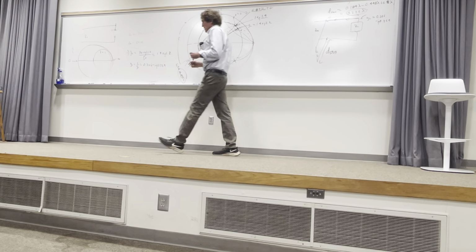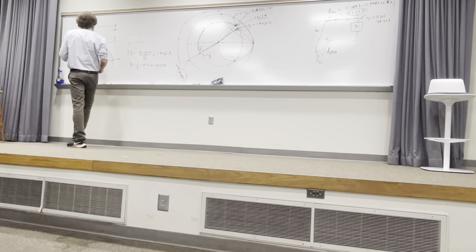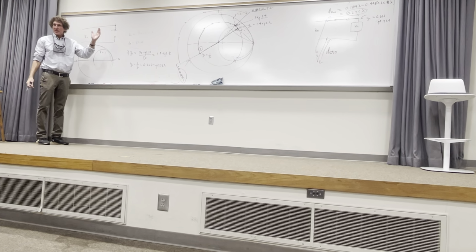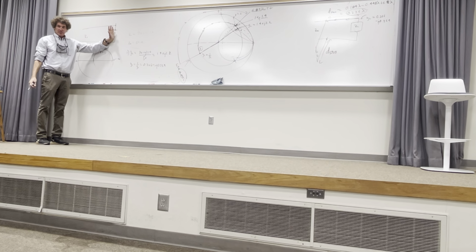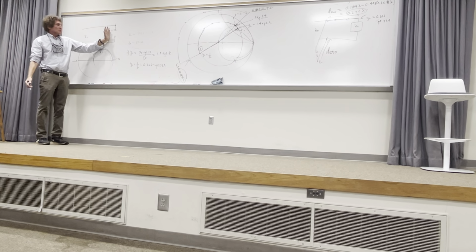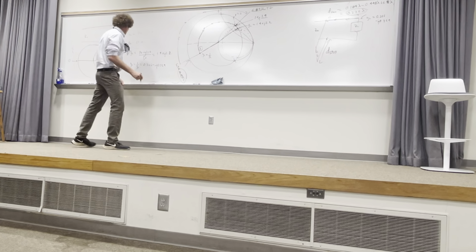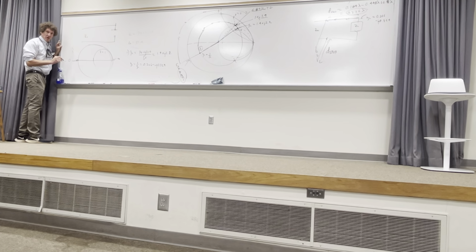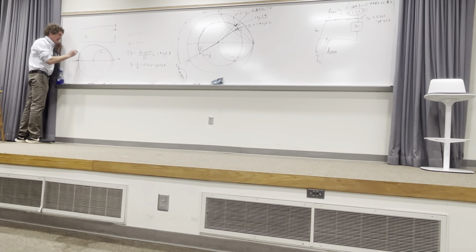Okay, so back to this thing. We're here, and I made the case, if it's an open circuit stub, then the impedance is infinite, the normalized impedance is infinite. The admittance, the normalized admittance is 0, correct, class? How far do I have to move? Here's where I'm going to start. I'll do it in this one. I'm going to start right here, right? Y'all follow me? That's 0.